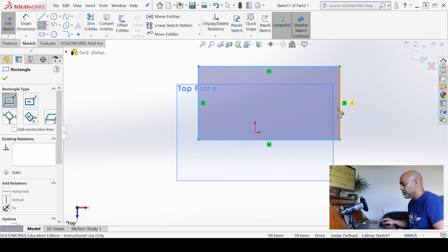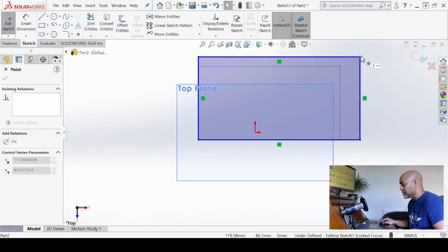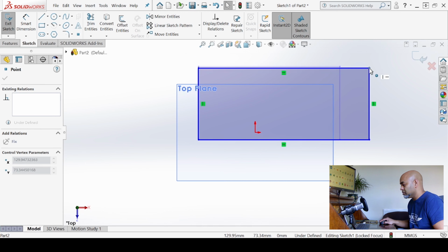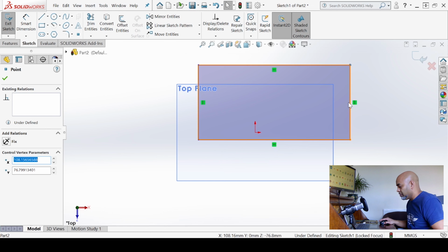Now, you have in the previous parts looked at the fact that there are some geometric constraints here which show you the way this rectangle will function and behave. For example, it is allowed to scale up and down like this. It's allowed to grow in those particular axes here, but I can't rotate these lines without getting rid of these indicators. So, that's one way of constraining your design. A good designer is always looking to specify as much detail as necessary to be able to give all the information to the manufacturer about their design.